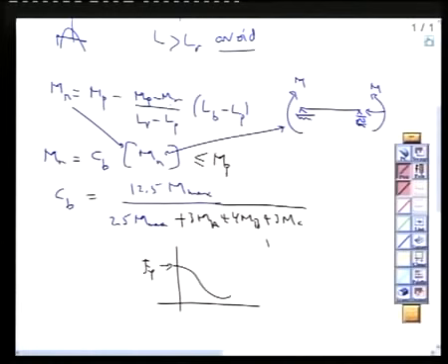Any questions? These are the main ideas concerning design of beams. We gave you tables for Lr and Lp if we have A50. In case we have A36, and today I will solve a problem with A36, it is easy for A36 to calculate Lp.